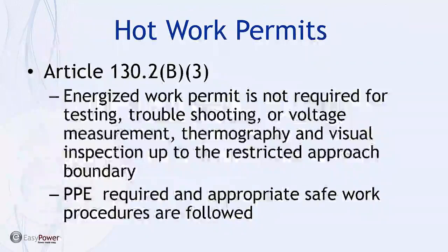Now before anyone jumps on the computer and texts me, "Great, Jim, send me a copy of a hot work permit," let me say that I'm not the person who can make that recommendation. Most often, even the engineer who designed the building may not be the best reference for this procedure. The first person I would turn to, and the person who best understands how your system works, should be the lead maintenance electrician, whether he or she is a contractor or not. It's that tribal knowledge of the system combined with a better understanding of how the arc flash phenomena affects the system itself that has been the missing link.